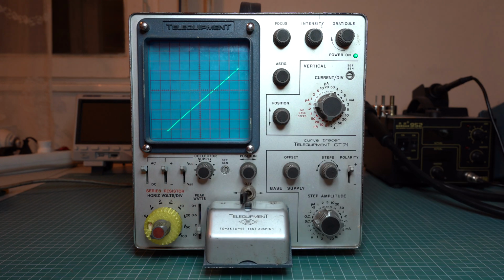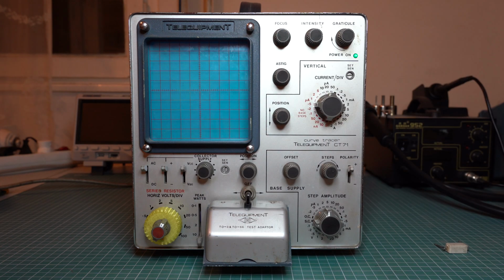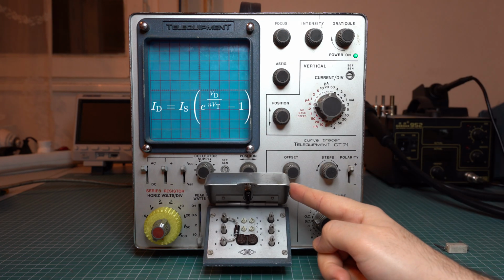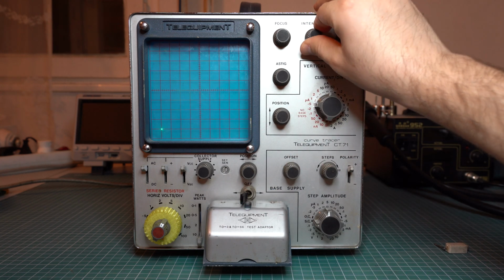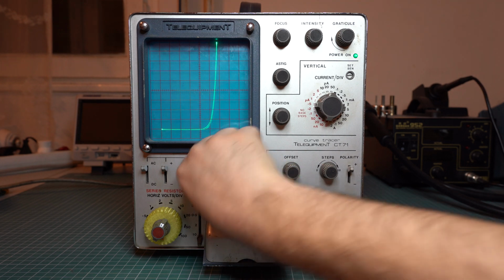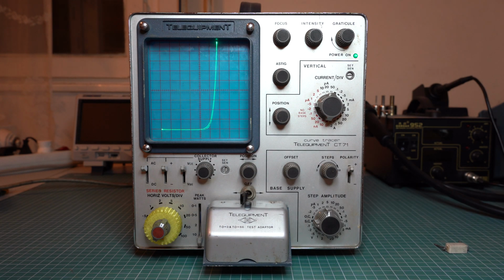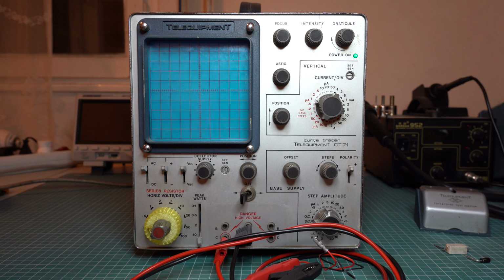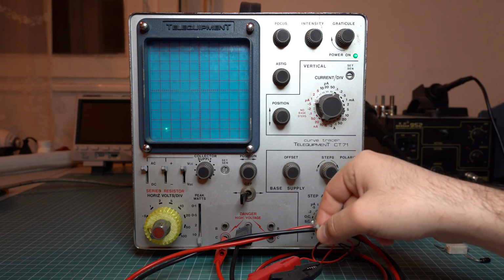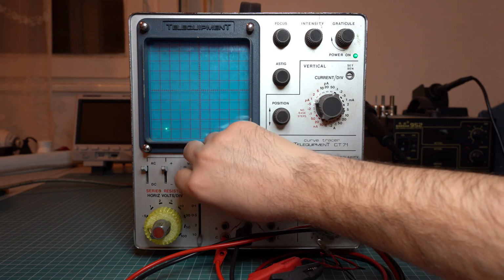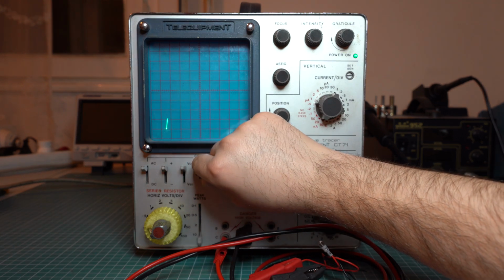And as expected, we get a characteristic straight line that the curve tracer produces for all resistors. So let's see what the diode looks like. According to Shockley's diode equation, we should get an exponential, right? And sure enough, we get a characteristic exponential of a diode. And just for fun, let's characterize an incandescent bulb as well. So I have this small incandescent bulb connected to the curve tracer, and let's increase the voltage and see what happens.